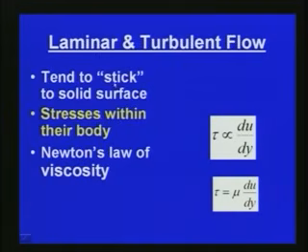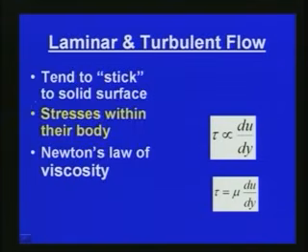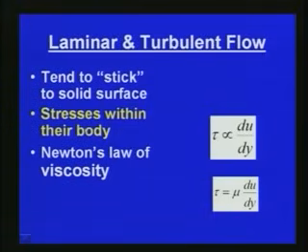With respect to this, due to the viscosity or the viscous effects, the fluid tends to stick to the solid surface. In the previous slide you can see that due to the viscous effects the fluid tends to stick to the solid surface on both sides, and due to this sticking effect, or no-slip condition, a boundary layer is created. The flow pattern can change whenever a flowing fluid is interacting with a solid surface.